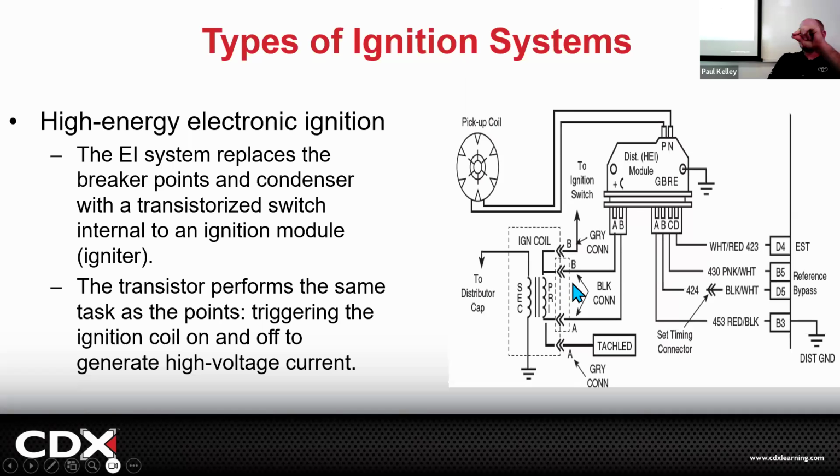It was making the ground and taking the ground through this ignition module. That was its job. Okay, see the progression there? So if you had an ignition module that wasn't pulsing ground, don't you think it could be the pickup coil? The pickup coil has to induce a signal to show you where cylinder 1, cylinder 2, cylinder 3, cylinder 4, cylinder 5, cylinder 6 is, right?